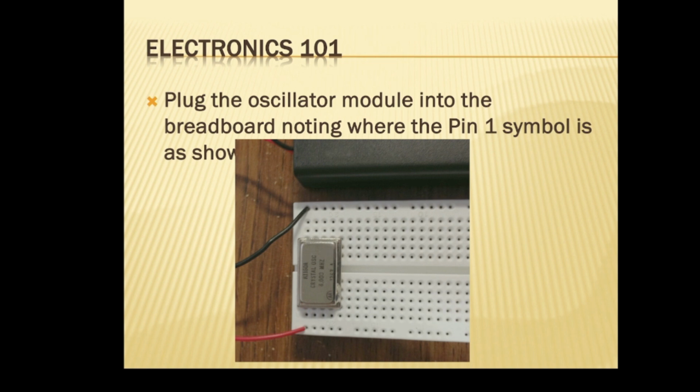Okay, so we pick pin 14, 1, 7, 14 goes to positive, that's correct. Pin 7, 1 through 7 goes there and goes to ground. They're the same row? That's correct. And then the output is on pin 8, which is that one. And the ground goes to ground. And there's nothing hooked onto the one that says Motorola.